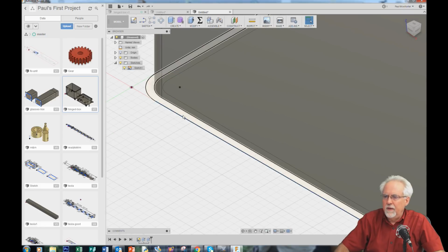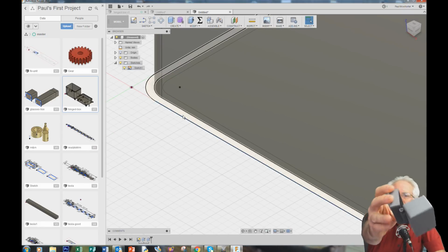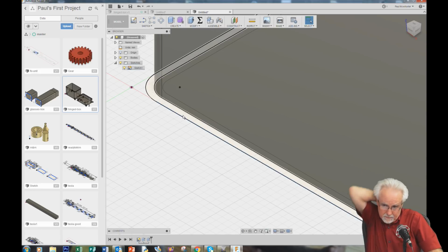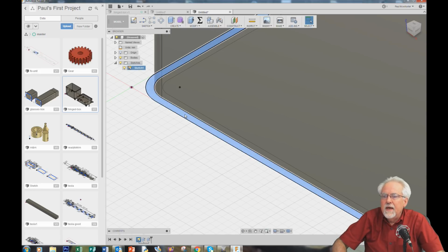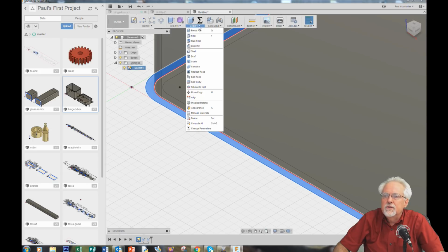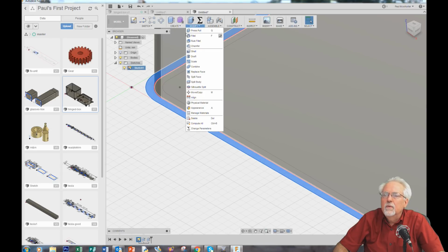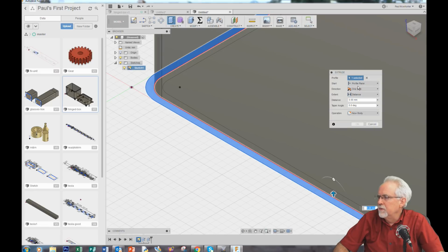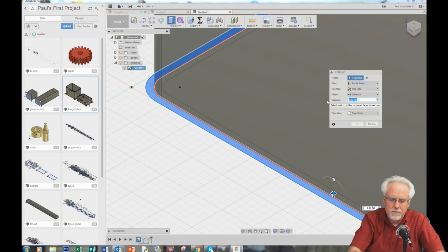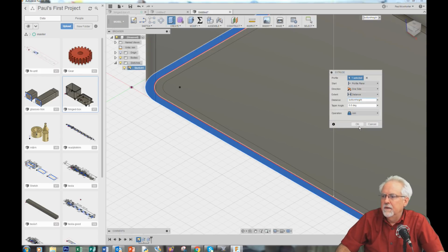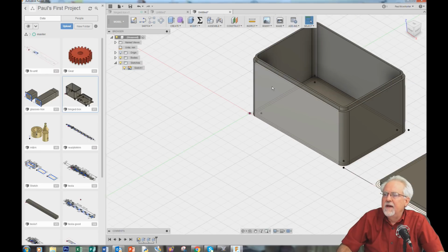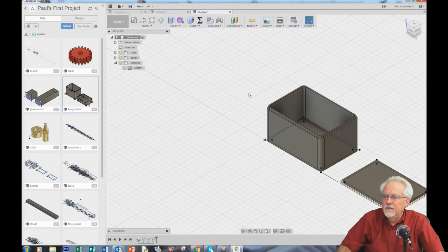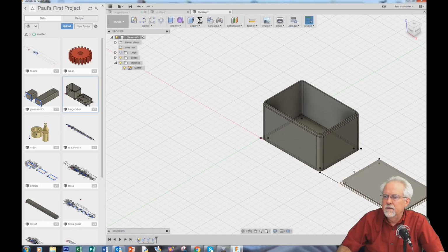Now this one on the outside ring, that's just going to be the bottom height without the lip height. Okay, so we're going to click on that. We're going to say extrude. Where is that? It's under create, extrude. And what are we going to do here? We are going to say that distance is going to be bottom height. All right, there, boom. Now that is done. That is really, really slick.